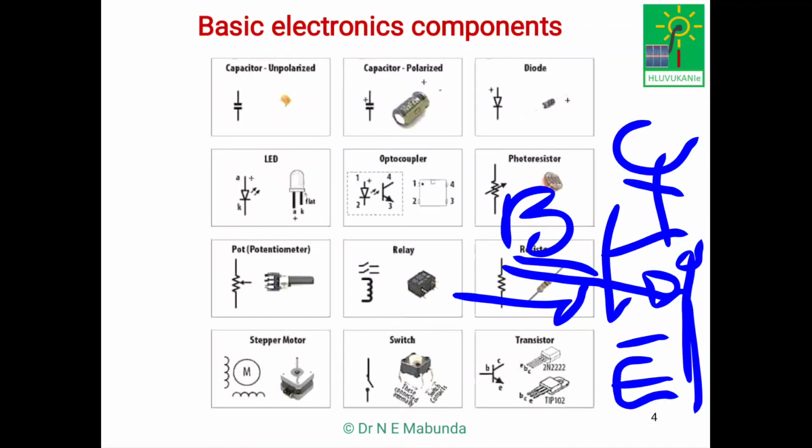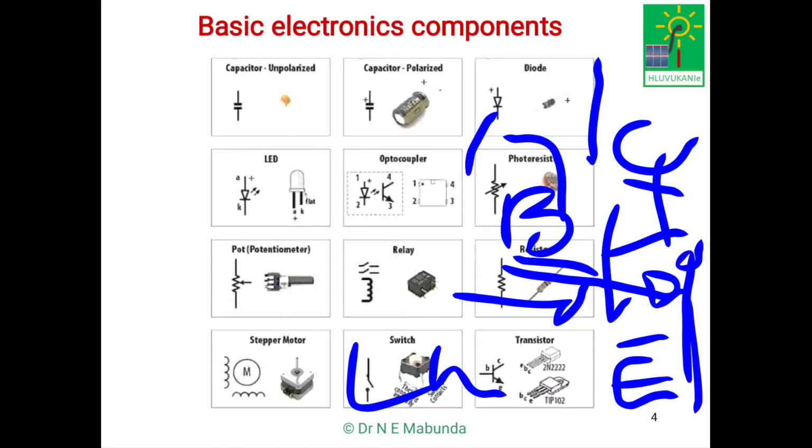So you can grow this small base current slowly, and then you have the output changing slowly but in a larger magnitude. You are amplifying. Or you have the base between two instances, high and low. When you apply low, it's off. When you apply high, it switches on at the high voltage. Maybe let's say you use 1 volt to switch on 20 volts.